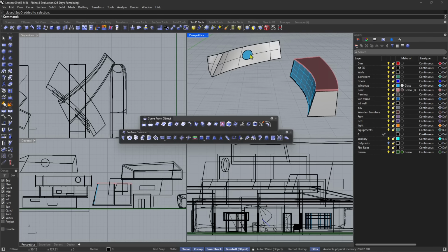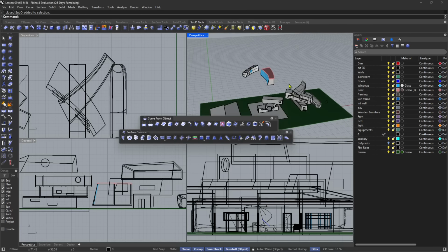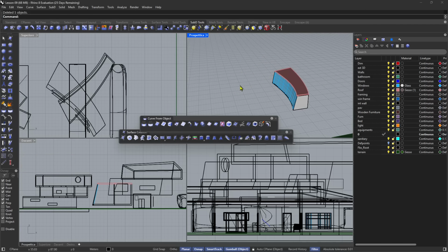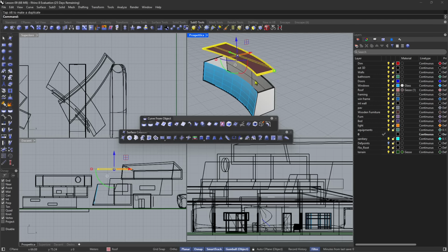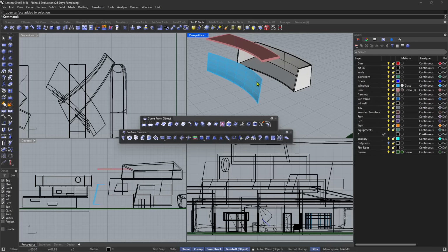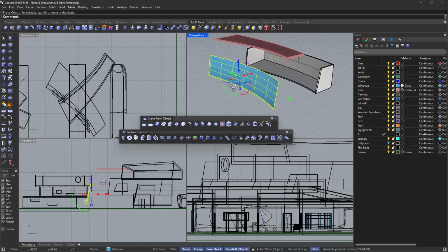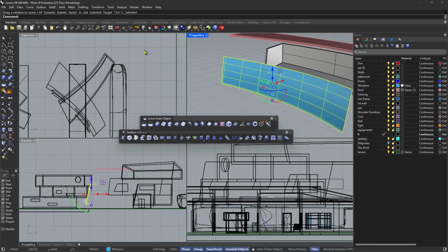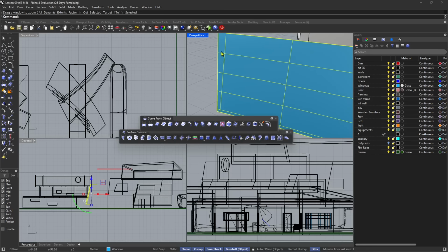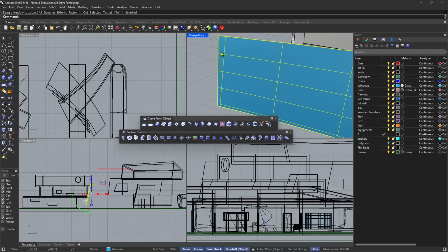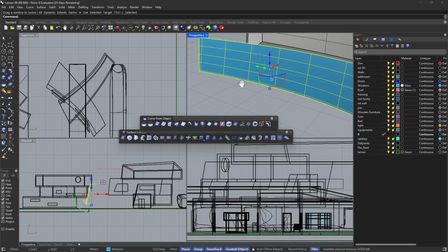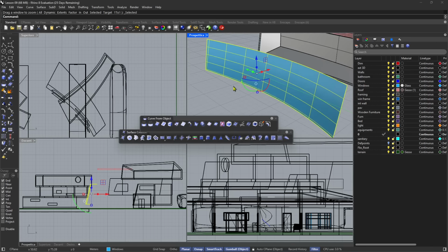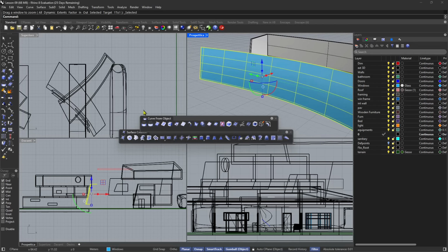So we also projected and trimmed some openings from the generic mass, and then we started with the basic object, and then we separated the various parts, so the walls, the pavement, and the facade here, like a curtain wall. And also we had a little problem here. If I zoom here, you can see that we have kind of an extra little thing, which is not really great. But at any moment, we can reconstruct a surface, and we can use more advanced tools in NURBS modeling. And we're going to see some of them right here, surface creation.